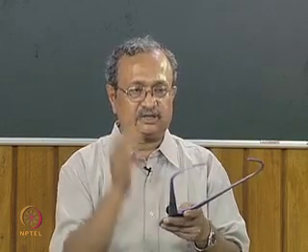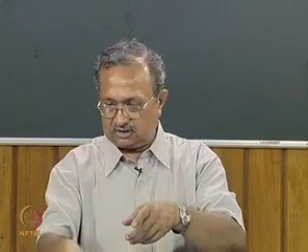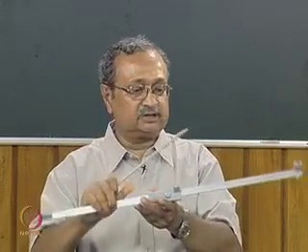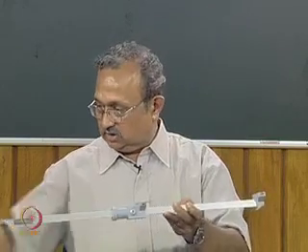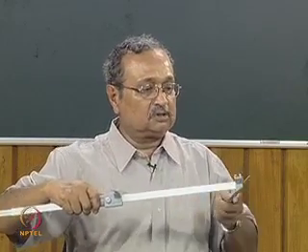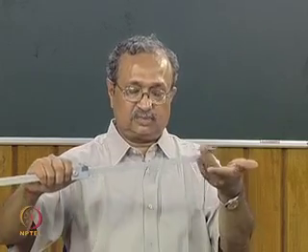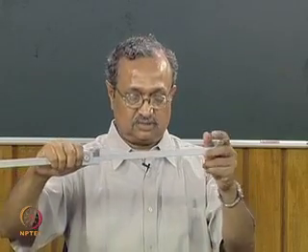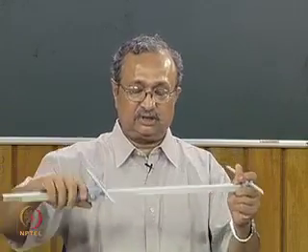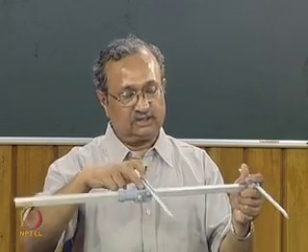In certain cases where we need to measure group distances, where the measurement is not possible with this type of attachment, normally what happens is that, keeping one side fixed and sliding the other side like this, with the body in between, we can get the total measurement dimension from here.